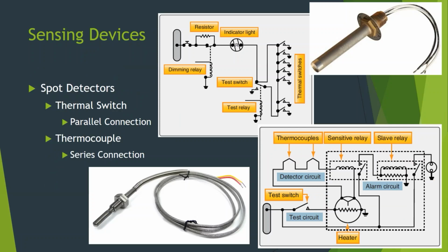Or newer versions of these, what do you think they use in place of these relays right here? Solid state. What's replaced relays in a solid state circuit? Come on. Basic electrical here. The logic gates are just a way of describing logic. It's a type of semiconductor. It's got 3 wires hooked up to it. A base, an emitter, a collector. What am I describing? It's a transistor. So a lot of these sensing relays have been replaced by transistors now.